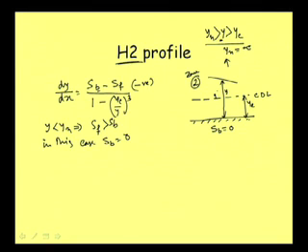And for the depth y in this part, y is greater than yc, so this ratio will be less than 1, and 1 minus something less than 1 is positive. So ultimately dy/dx is negative. So, a falling profile.